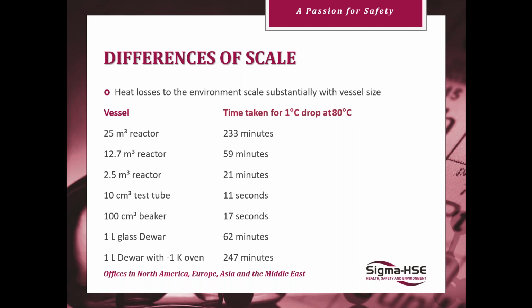We can see that as the reactor size decreases from 25 cubes down to 2.5, the time the vessel takes to drop 1 degree, starting from 80 degrees, goes from 230 minutes at 25 cubes to just 21 minutes at 2.5 cubes. So that's an order of 10 with both the reactor size and the time it takes.